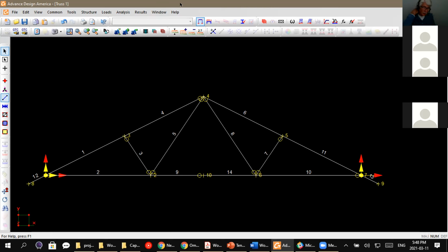Okay. So like I said, I always keep my visual graphics on until my model is completely finished. And then after that, I move on to my loads. And once my loads are completely on, I move on to my load combinations. And then I move on to my analysis. So systematically, and guys, do your sketches in front of you. Don't try to do it in your head what the dimensions have to be. Write all that information down on a sketch and then go put it into the program. The program just wants input. It doesn't want to do anything else.